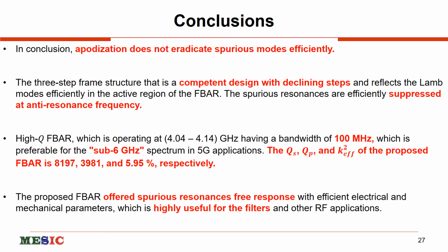The conclusion is that the apodization technique does not minimize the spurious mode efficiently, but it obviously minimizes it. So the three-step design is the competent design with declining steps, and it has a high quality factor and high electromechanical coupling, and the proposed design is highly useful for filters and other RF applications.